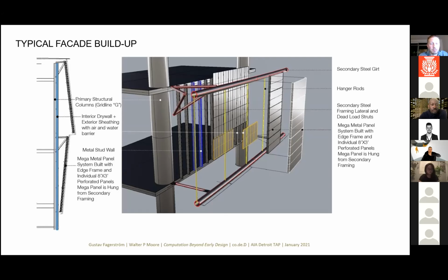So our system comes into play at that interface, where these struts, if you see the double triangle here, create a moment connection, so that this top horizontal tube, which was known as the hoop, becomes a moment stiff gravity connection. So that's where all the self weight of the whole system is taken up and goes back via these struts here into the primary system.